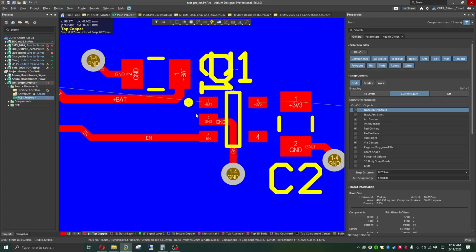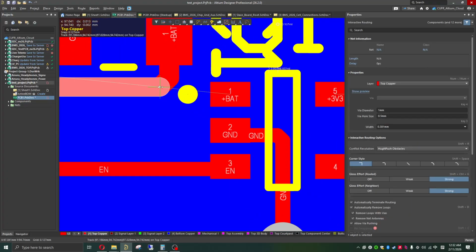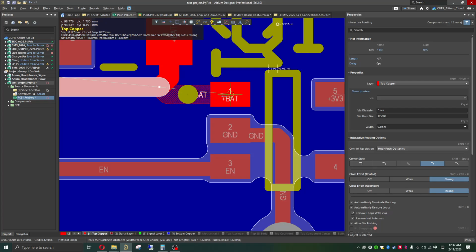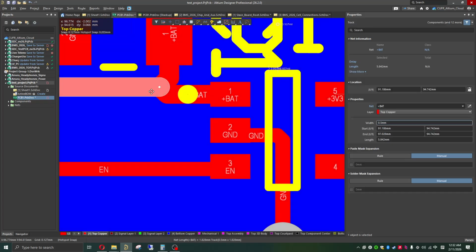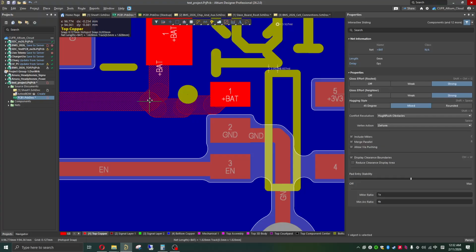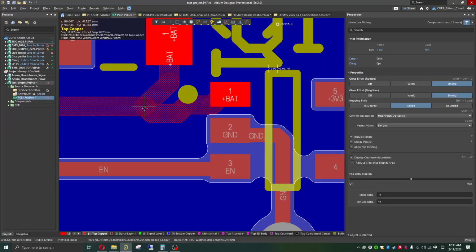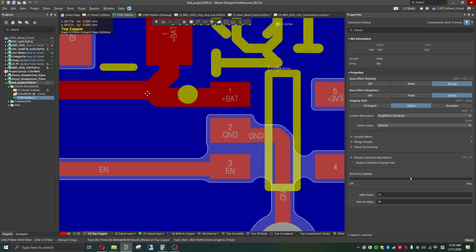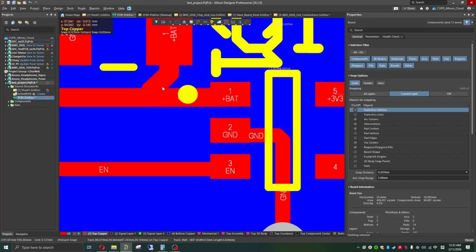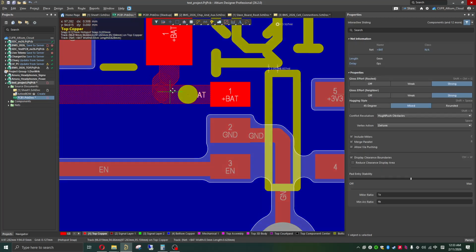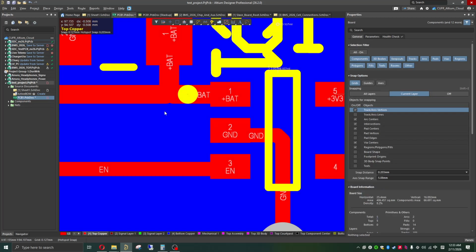Alright, now we'll do the same thing and make a trace that's a similar track width. You'll see that because I've already configured it for this node, it's already set at the proper track width. And I just want to straighten out this junction, like that.